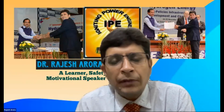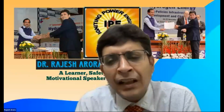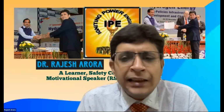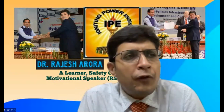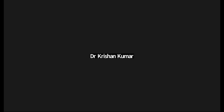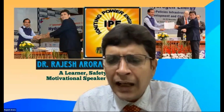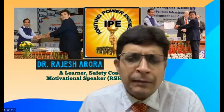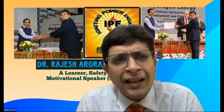Actually, what happens sometimes the substation people provide you the base MVA, short circuit MVA. That seems to be on the higher side, but actually there are some limits for a 400 kV system: 63 kiloampere is the maximum limit. For 220 kV, 50 kiloampere, for 33 and 66 kV, 31.5. Likewise, there are some limits. That can't be beyond that, because there are so many impedances coming.